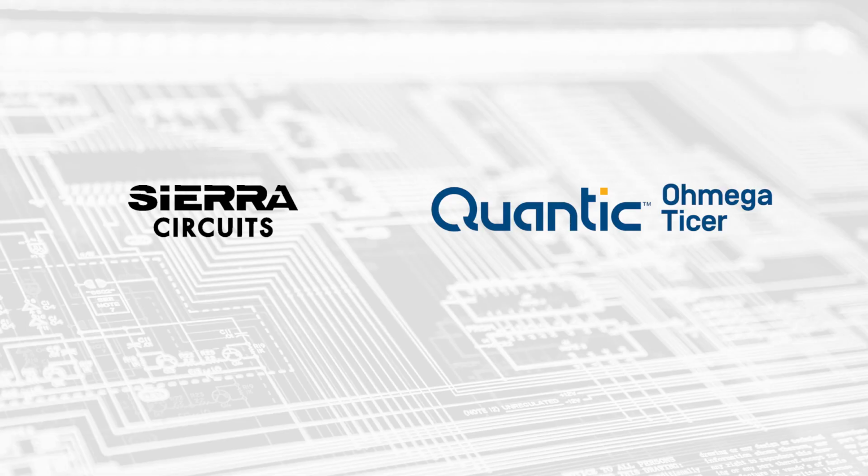Yes. The resistor layer does cover the whole board. So it's a subtractive process. When we put the resistor layer, it's on the entire copper. So what happens is that when you do the first etch, we remove a lot of the background resistor material, but the resistor material is still under the traces. Then you just open up on those traces where you want the resistor to be. But yes, it covers that whole PCB layer, and then whatever you don't need as a resistor gets removed.